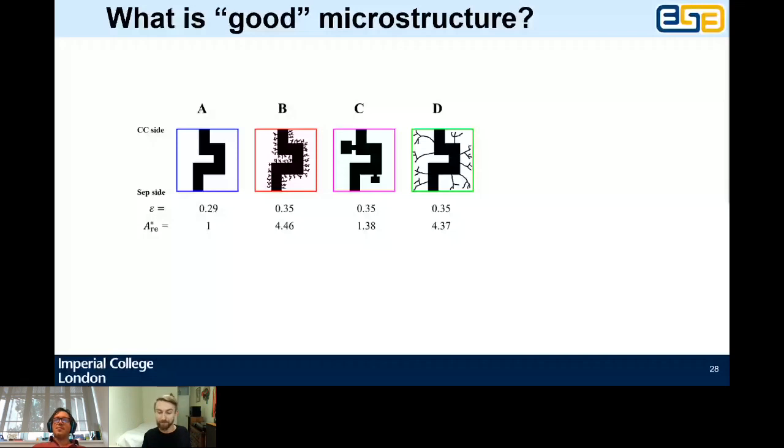But of course, in a battery, what you're really trying to do is get out of the interface on one electrode, across to the other side of the cell and into the interface at the other electrode. You aren't trying to flow all the way through an electrode and out the current collector. That isn't what you're trying to achieve. So why do we use a tortuosity metric that models that exact behavior?